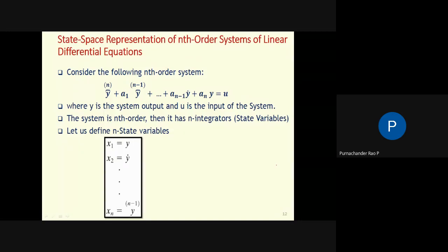So now we'll look at the state space representation of an nth order system of linear differential equations. Consider a system: y to the n dot plus a1 into y to the n minus 1 dot, and so on, plus a n minus 1 into y dot, plus a n into y, is equal to u.